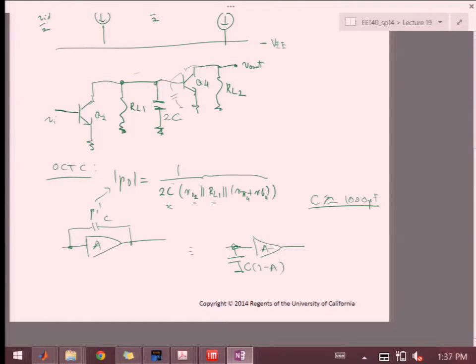It's assumed that the gain is negative here. And for our single stage, you would get something like GMRL1, or GMRD, it's all the same, or minus G. So essentially your C will be boosted, amplified by the gain of the stage. If the gain of the stage is 10 or 100, there you go. You can use 10 or 100 times smaller capacitance to do effectively the same job, right?